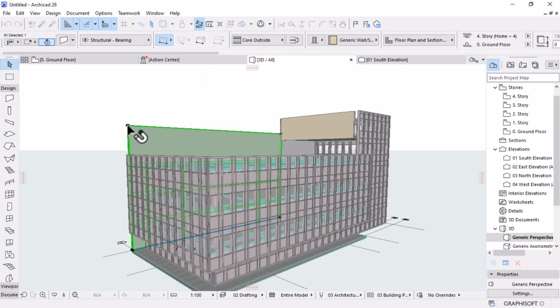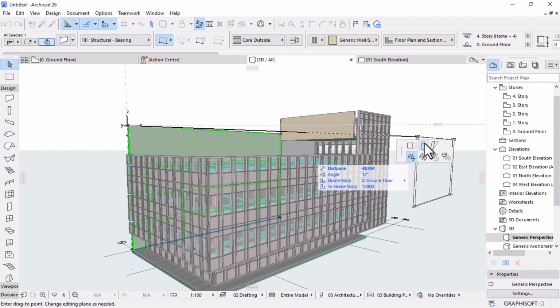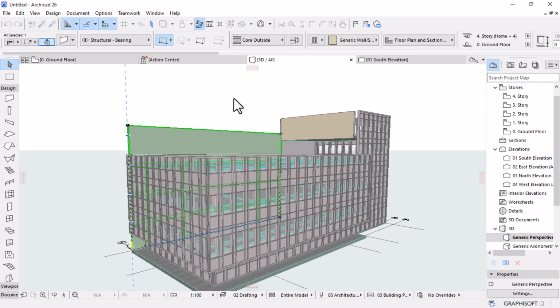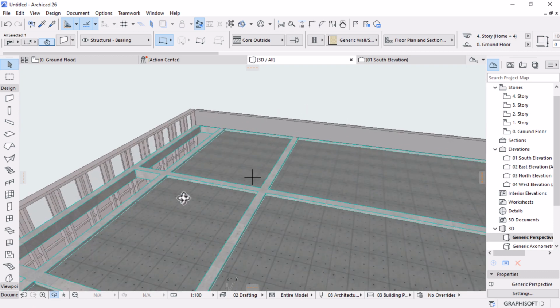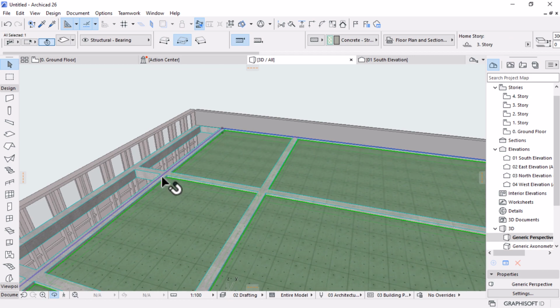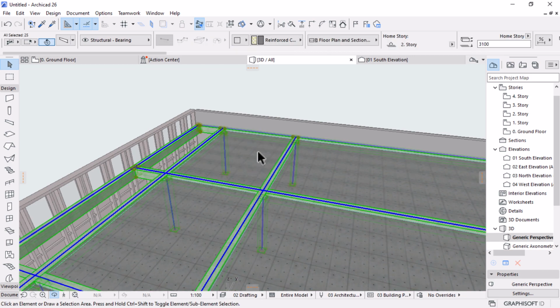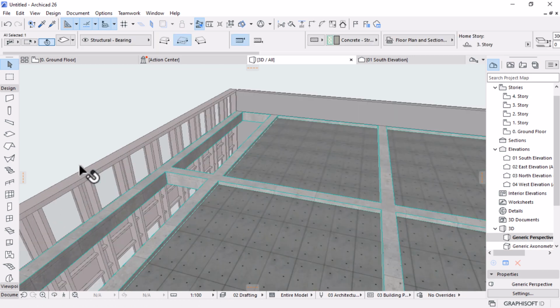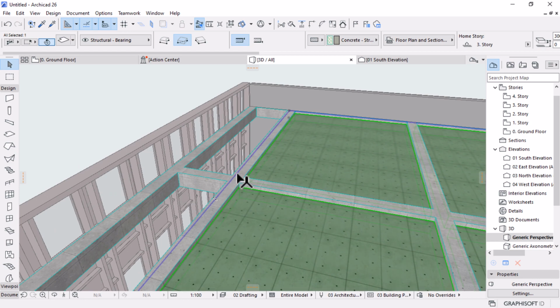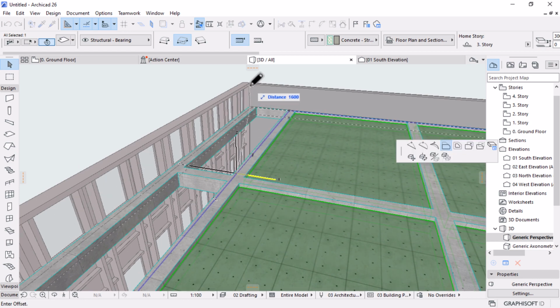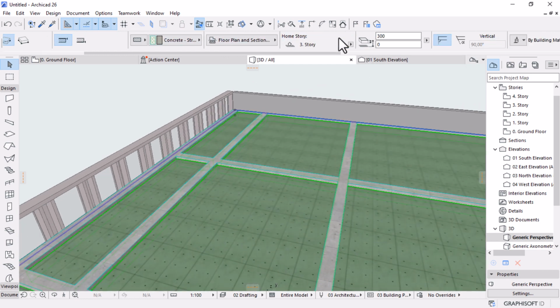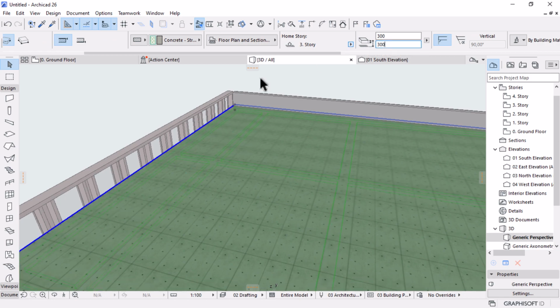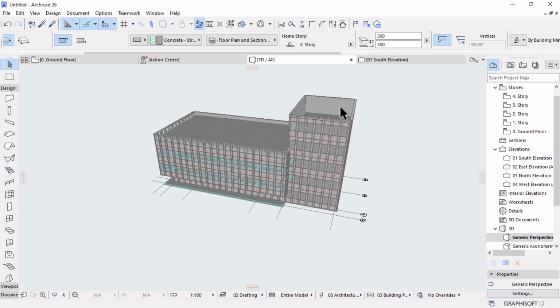And then I'll select this wall, also bring it down to the height of the curtain wall. Right, so for the slab, I'm going to select this, stretch, oh sorry about that, I want to select the slab. Let's pick the edge and stretch it all the way to there by offsetting the edge. And if you scroll in your info box here, let's make this to be 300 high. Okay, so that's basically that.